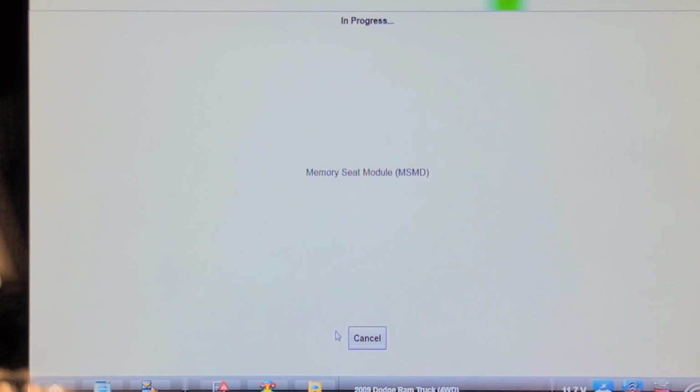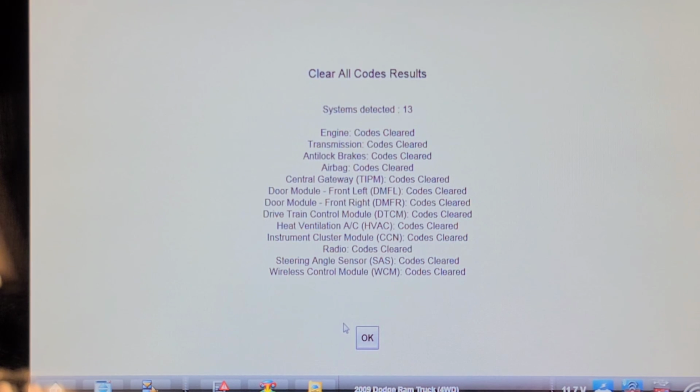Headlights seem to be working fine. Those codes could be in there from when a headlight failed in the past. For other products, you have to clear the codes, key on, engine off.